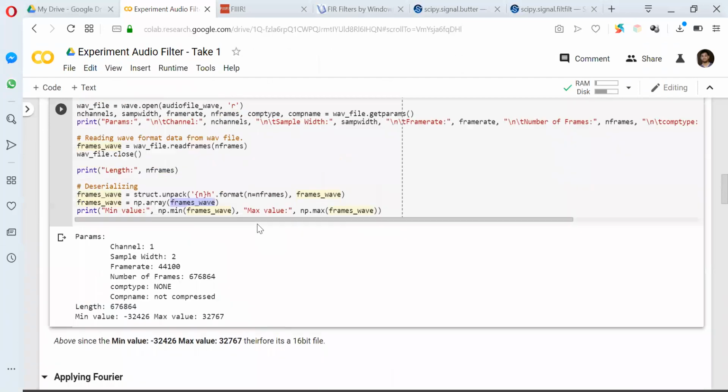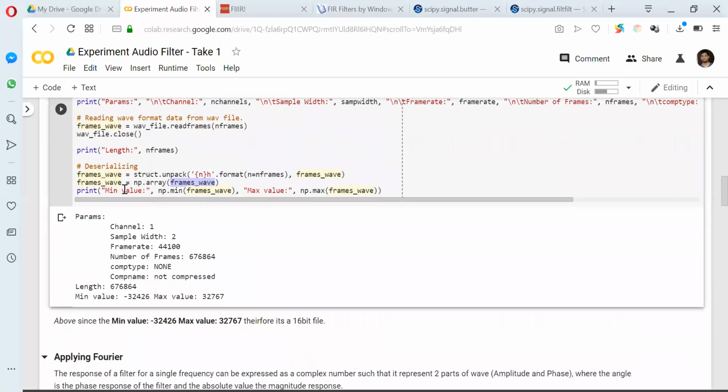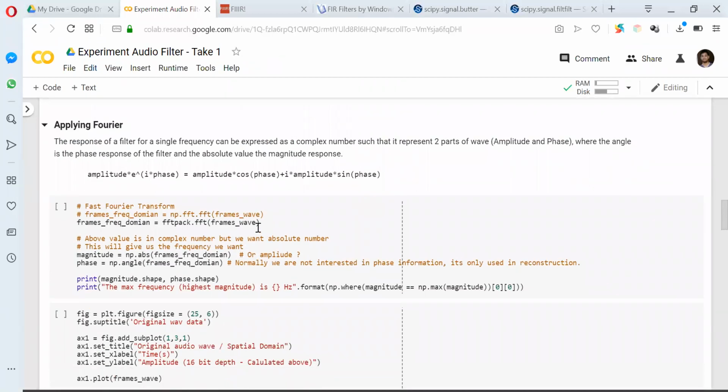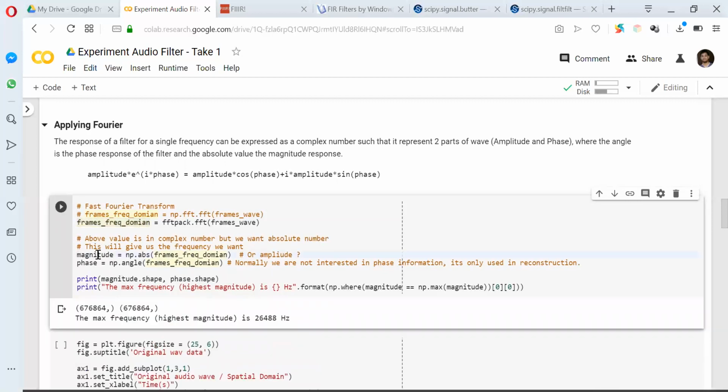It's really easy to use. All we need to do is use fftpack.fft, which should be imported like here, from scipy import fftpack. So it's an inbuilt library. We don't have to do anything. It is going to convert these sinusoidal waves into a complex number format, which has two different things: a magnitude and a phase. So what are magnitude and phase? Magnitude is kind of the energy of each frequency, and phase is the angle. So we use this information to play with the signal.